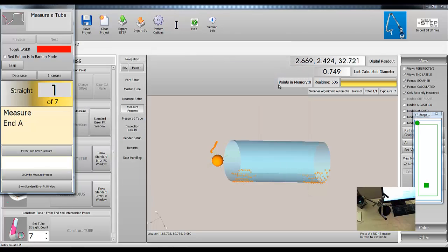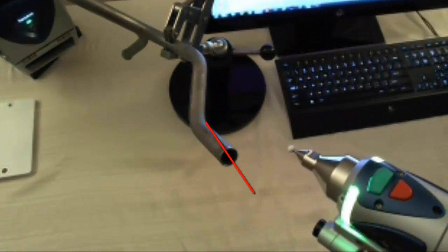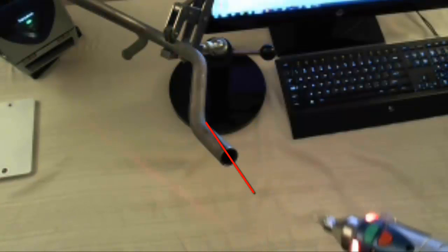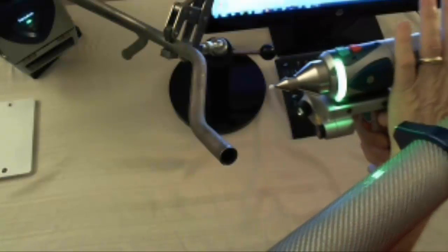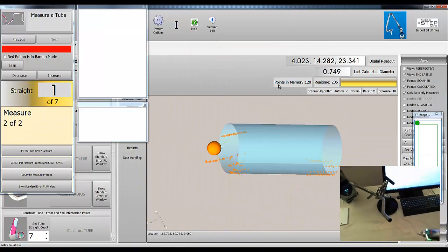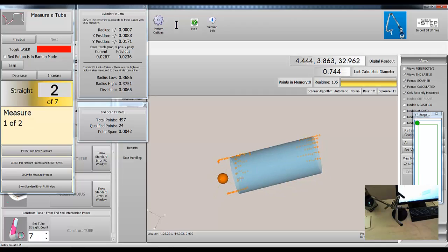This is a second end scan technique that I don't recommend. The reason is because it gathers far too many points that are not actually the end wall. This technique increases the possibility that VTube-LASER may choose the wrong point for the end scan projection.